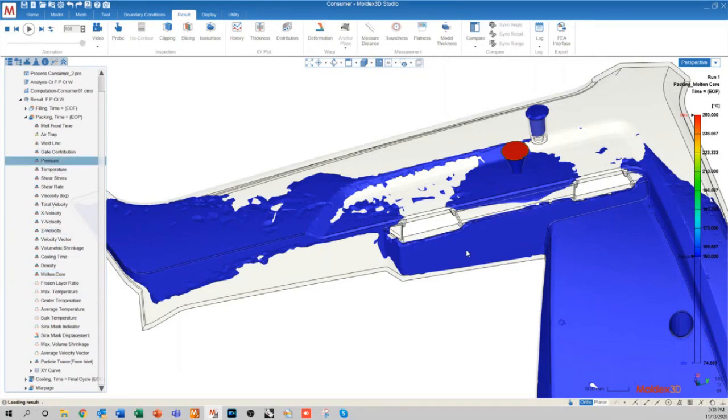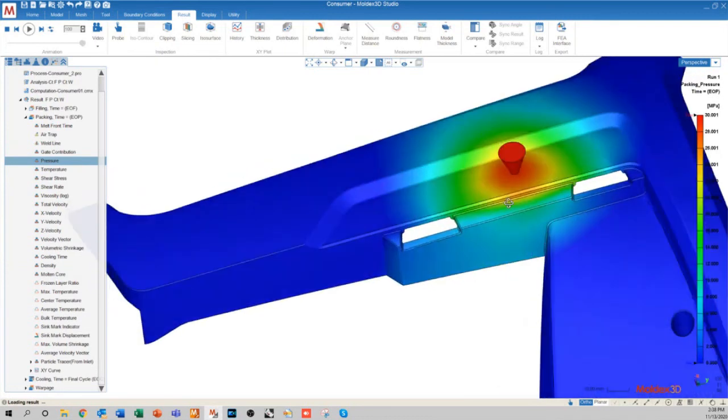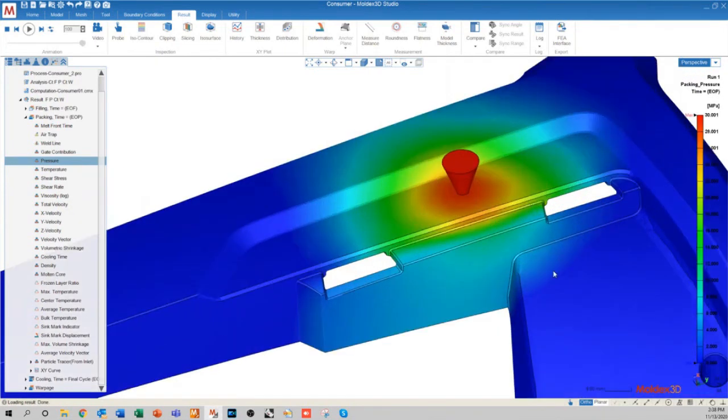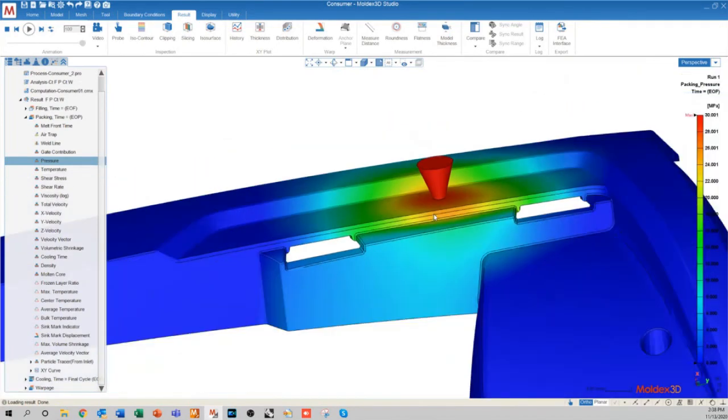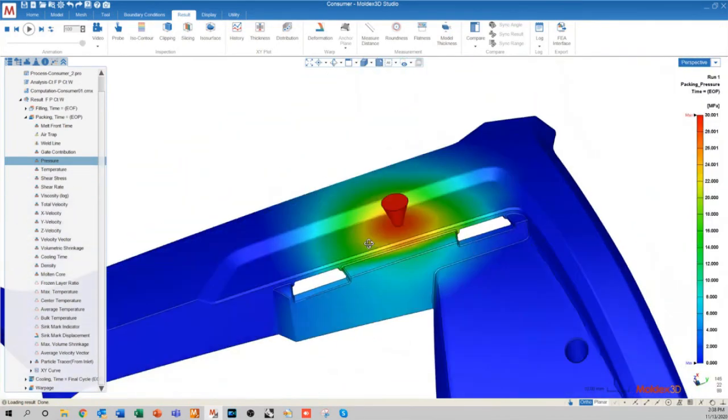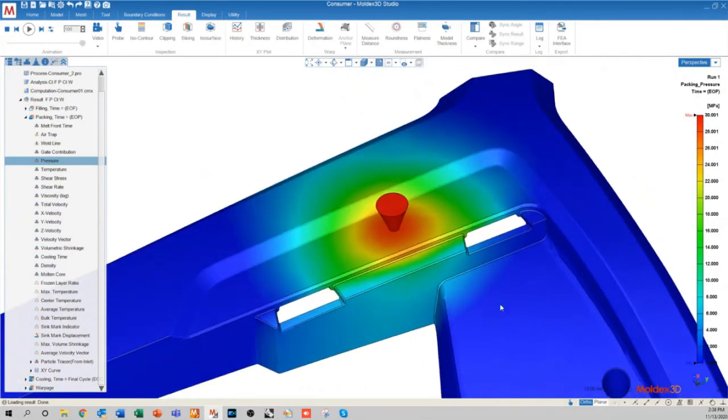And this sort of pressure concentration that we're seeing is actually a really huge problem, especially if I apply this pressure for a long amount of time, because I can actually shove so much material into my part geometry that when my mold opens, the material actually expands. And this is not only dangerous, but it causes the part to deform very obviously. So the dimensions of the part actually increase, whereas normally you would expect they would decrease based on the shrinkage of the material.